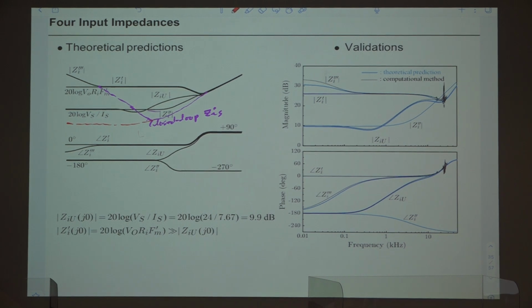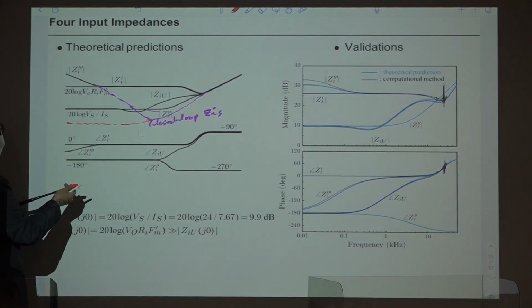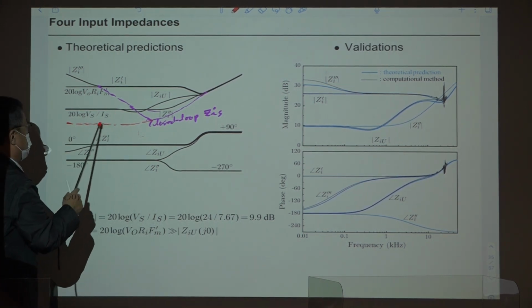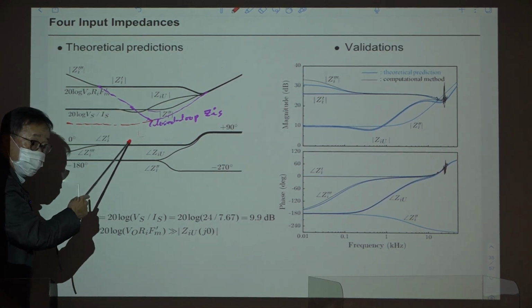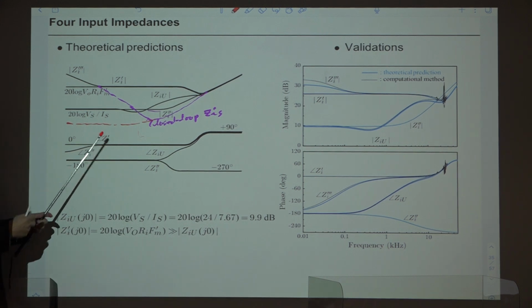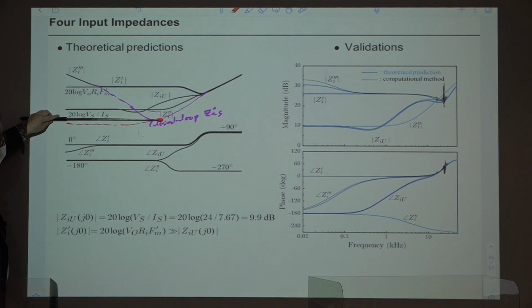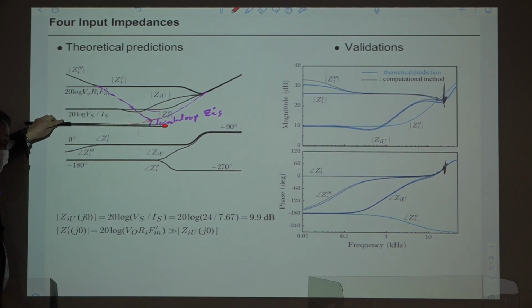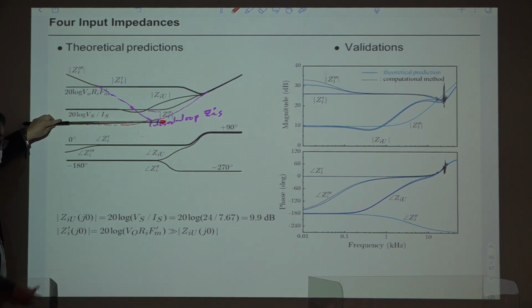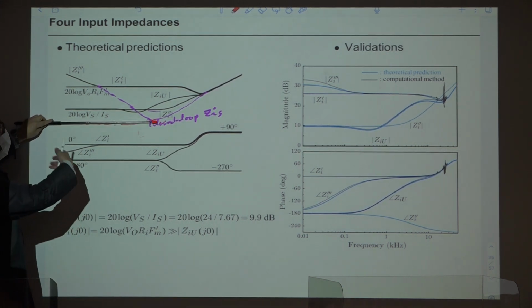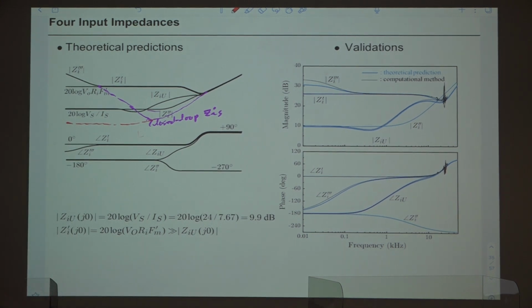So to maintain stability, the output impedance of the in filter must stay below this line, okay? That is the requirement. But if you obey that rule, and the maximum of the output impedance of your in filter falls below this line, then everything is fine. Okay, no stability problem, and there is no overlap. So this current mode control actually eases the problem of in filter interaction.